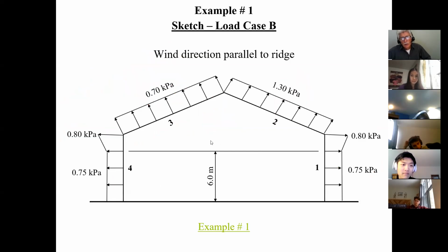And that would be, of course, the surface. Then you do the same thing for 1E. You redo your sketch, and then of course the wind is parallel to the ridge. You can't show the wind direction here because it would be perpendicular to your piece of paper, but you know that it's the wind parallel to the ridge. What's important is you show the right direction of the wind, and these are all in suction.